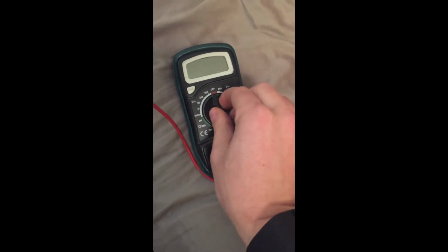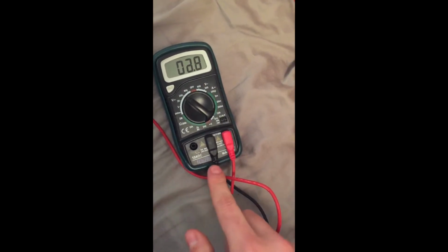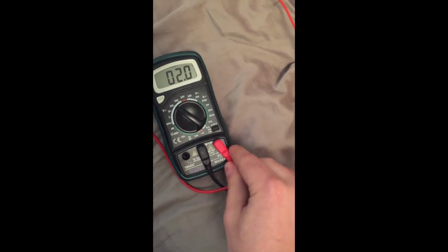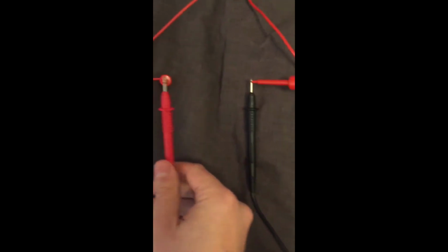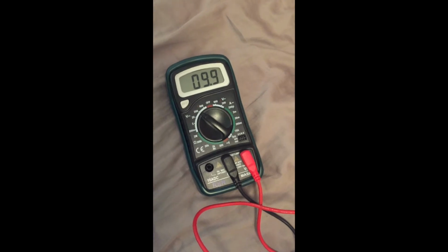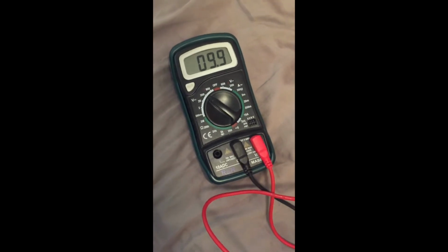To measure voltage, we want to put the digital multimeter to the voltage setting, have our common connected to common, and our positive lead connected to the voltage. Alright, here's my power supply. We'll be measuring voltage. You measure it in parallel, so across the circuit component. So you've got our positive and negative connected in parallel, and you can see that it's measuring a voltage of 9.9 volts,